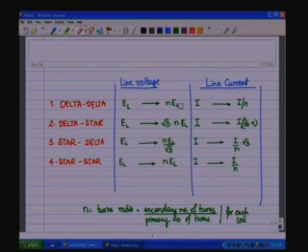Let us say you have a 400 volt system, and the windings of the primary side should withstand 400 volts and the windings of the secondary side should withstand n times 400 volts, because in the delta connection the windings come directly across the terminals or the line. In the case of the star, the windings are phase quantities. The voltage of the windings is 1 by root 3 times the voltage coming across the terminals.